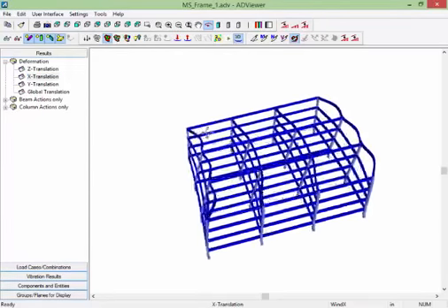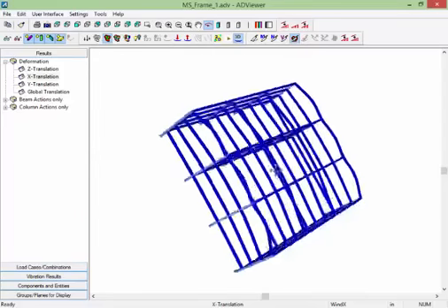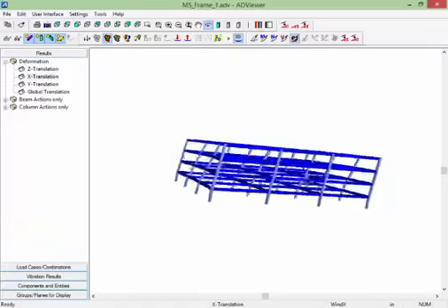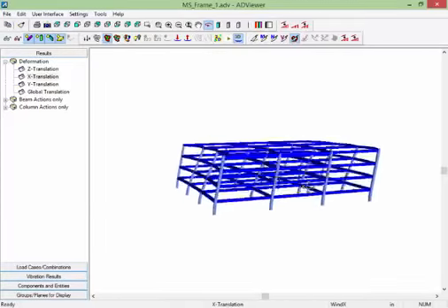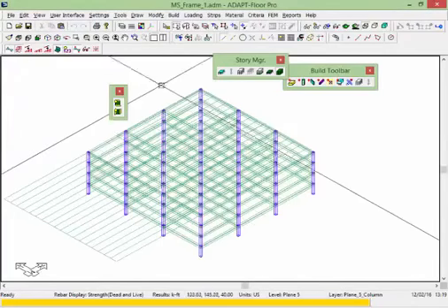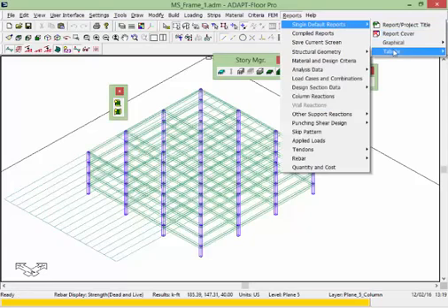So we can clearly see at the top level these beams are bending, they're in flexure and taking load out to the columns, and then these four interior columns are also displayed relative to the location of the outer columns. So clearly the loads are being applied. If we wanted to check equilibrium loads, we could go to Reports, Single Default, Tabular Reports, Analysis Data, Equilibrium Check. And this will actually show us what the applied load is in this case.